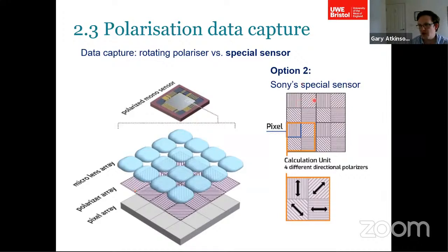So we break the image down into these units. Each unit will have one pixel with vertical polarization passing through, one pixel at 45 degrees, one at 90, and one at 135, and so on. Then a few simple equations can be applied once you've captured the entire image like that, to determine the polarization state at each point. Simple linear equations.